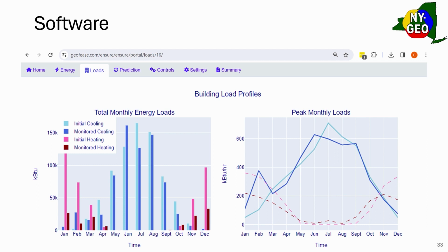But the problem with building energy models is you're using something static to design something that's dynamic, that changes over the years. What I mean by that is your static building energy model is just an assumption of how the building operates, so when the lights are on, how many people are in and out. But that's going to change throughout the year, after year of the system. And so if you have your BTU meter that you're pulling data from, you can compare the actual BTUs that the ground loop is seeing to the building energy model that was used to design the ground loop. And so that can be pretty interesting.